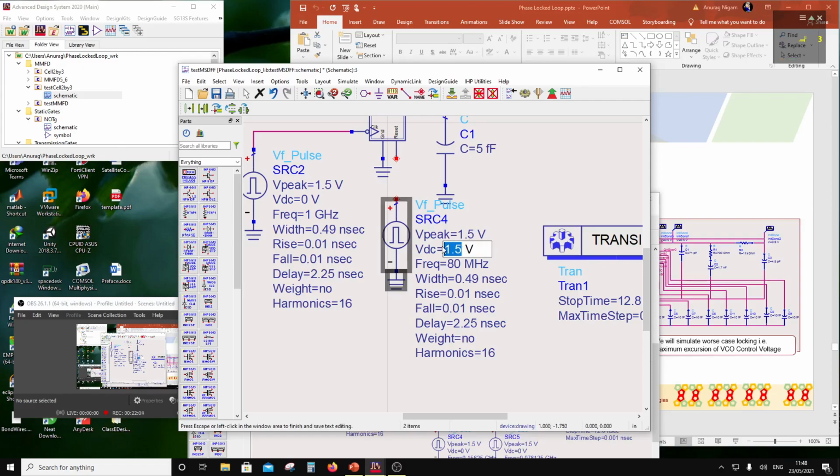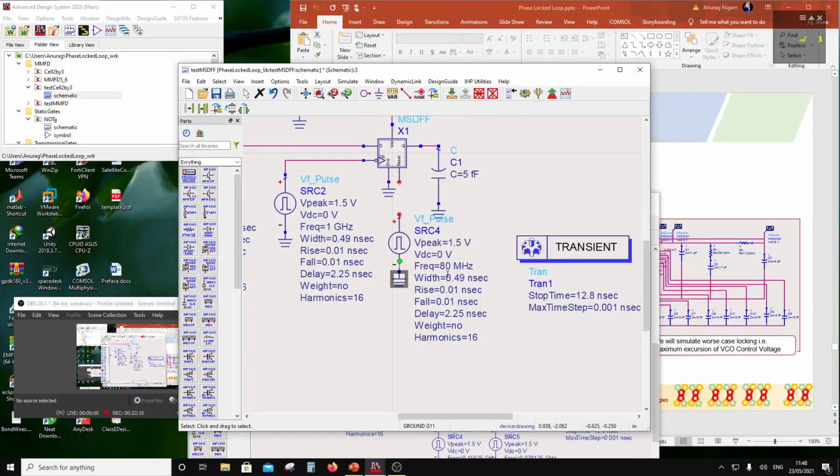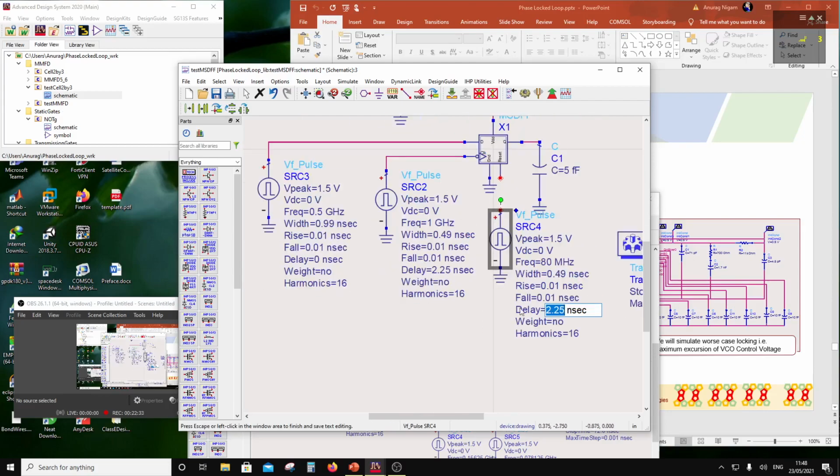Okay, so I have to reverse this, right? So how do I reverse this? Okay, so I'm going to introduce a pulse width of, let's say, 0.5 nanoseconds, so that's fine, and I'm going to give a delay of, so before I hit the clock, right? So I want to put here 1 second before that. I'm going to introduce that pulse, right?